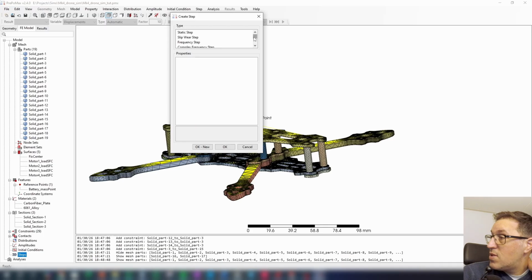And here is something that is interesting. Why is that? Because performing an impact analysis or a modal analysis, modal analysis is more straightforward, but an impact analysis is more complicated to perform. So there's a nice trick to simplify things. You can use the acceleration and transform it to a steady state force.